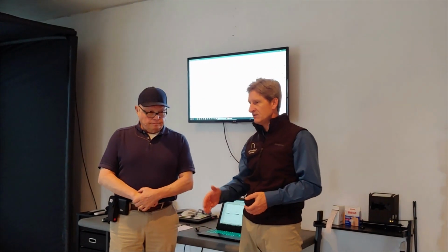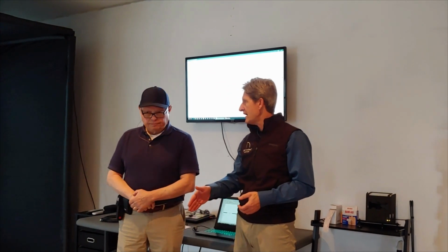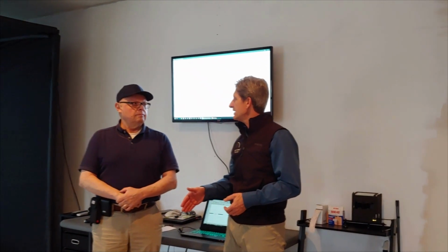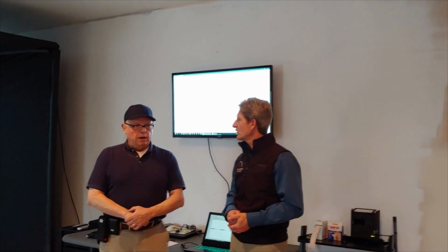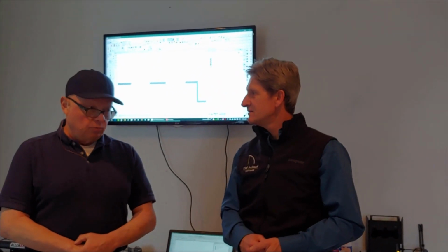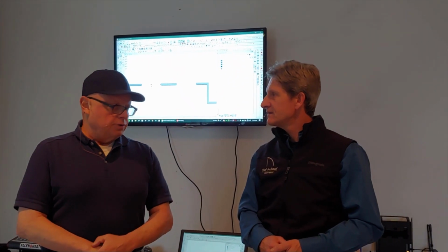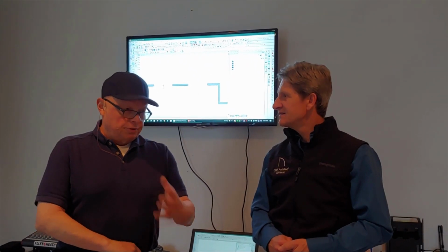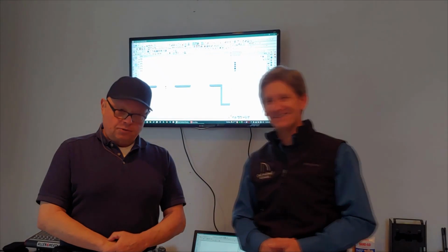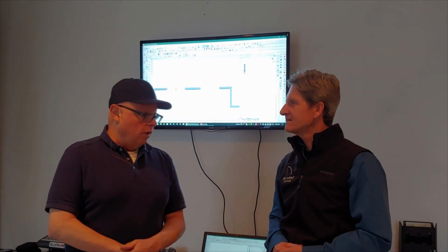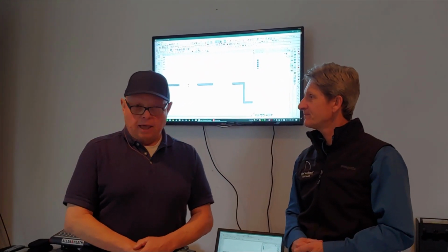Now, in this case, we have a condition where the foundation is stepping and the stem wall goes below the ground. What do you do about the location of the stem wall or the footing in that case? I don't worry about what's below ground. I have no way of knowing what it is. If I locate the foundation, it will be simply the stem wall, and I will say so. I'll just make a note, or I will simply use lines and say that what you see is the bounds of the stem wall. What you see is what you get. And then the other important thing there is how high the stem wall is above grade.